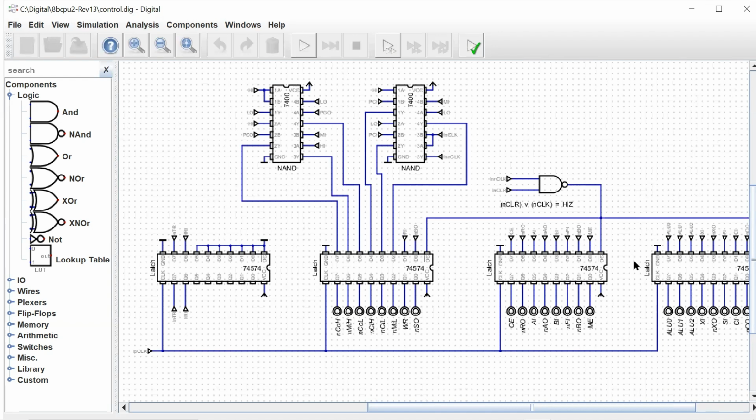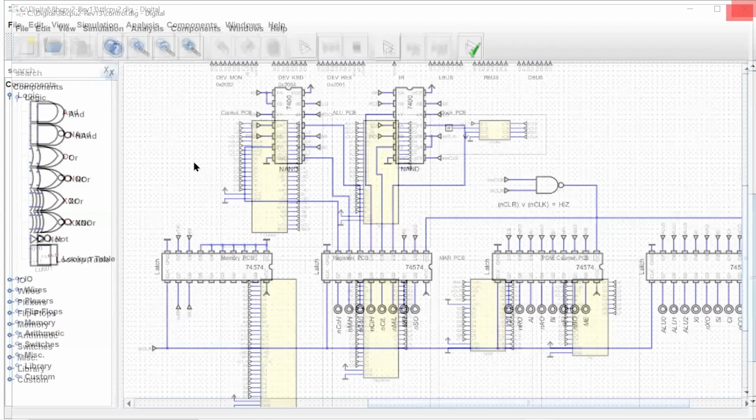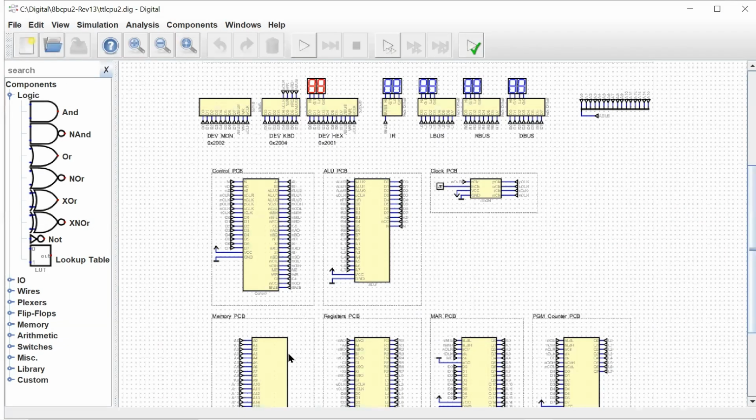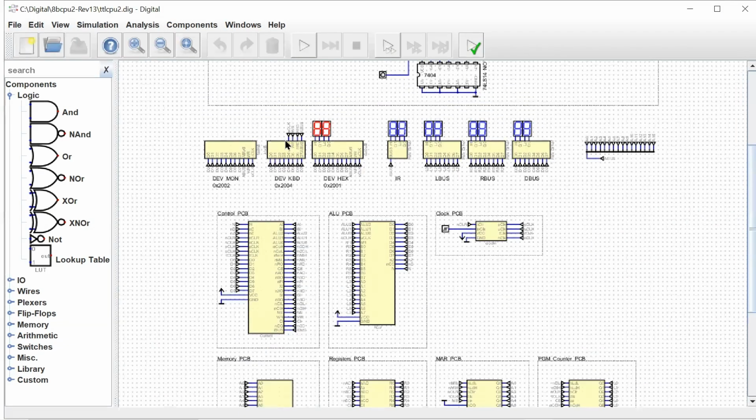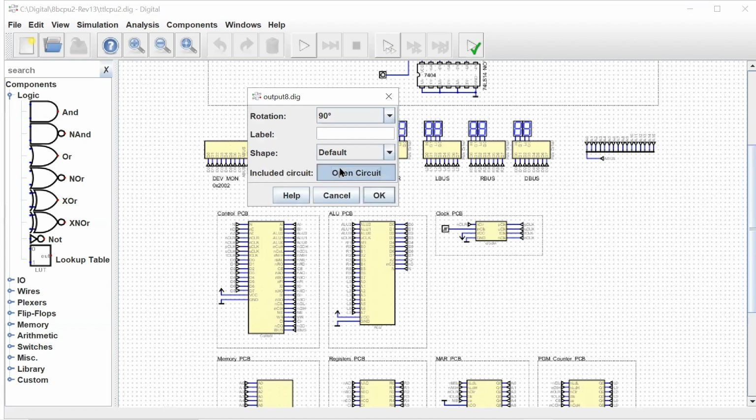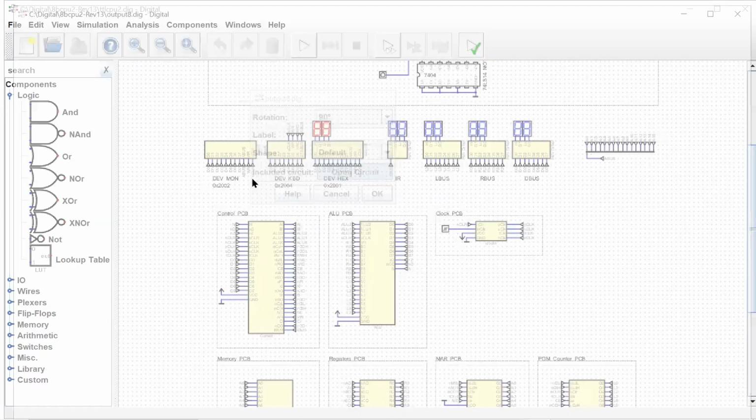But now, since these signals are all latched in the not clock, I could not do that anymore. So I had to make this just the write enable signal, and any place that we were doing an actual write, which would be in the memory circuit, or in any of our devices like the hex display.